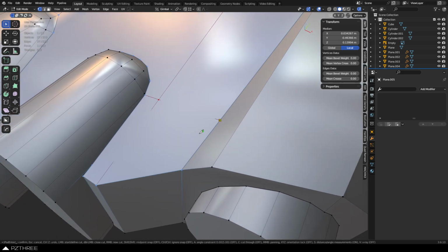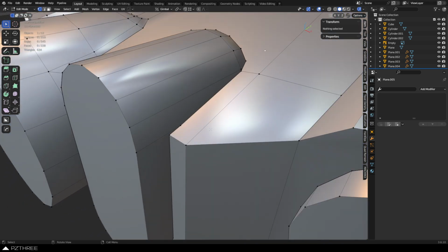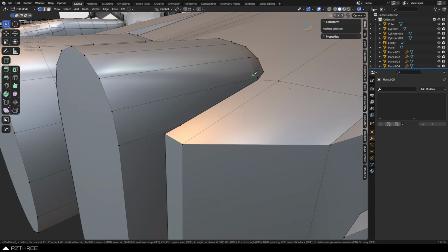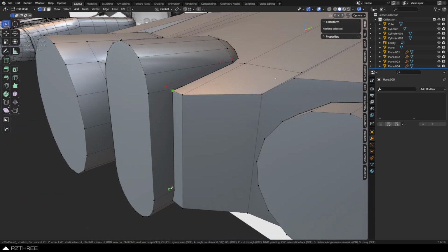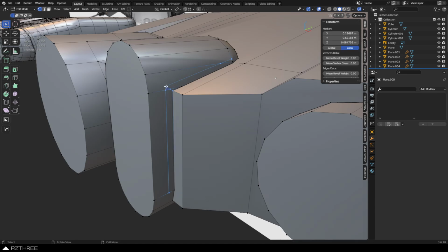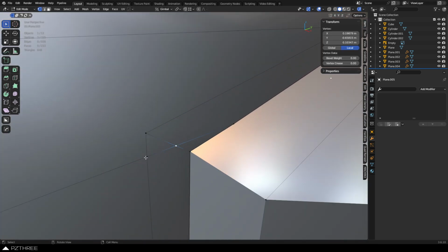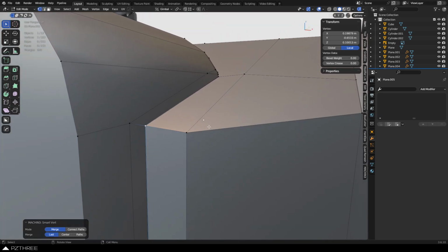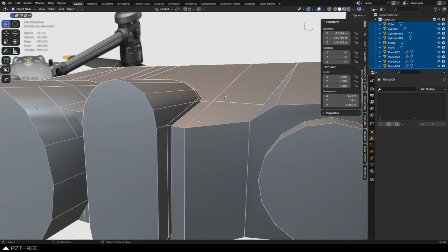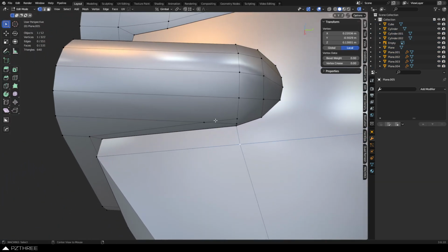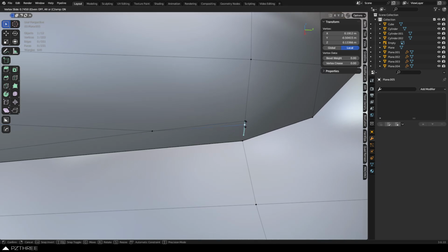The worst case scenario is you make some cuts and you find that later on you start creating uneven topology, like maybe the surface gets a little bit rocky or something like that, and you have to flatten things out later on, or you have to restart because you accidentally messed it up. But don't be afraid of your mesh. I think that's the biggest problem. A lot of guys get really afraid of making changes or edits. As long as you're being careful not to make non-planar faces too much, you can get away with a little bit, but if you make non-planar faces, it can make your surfaces look a little bit bad. You can usually correct them a little bit, but it can be a little bit challenging, to say the least.